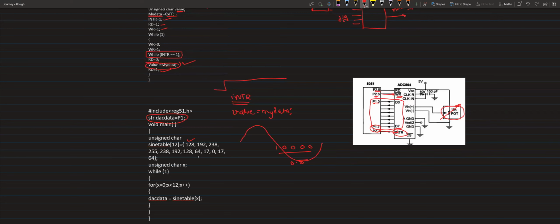If you pass these values, it is going to generate one sinusoidal cycle. So they have stored voltage samples, 12 such values. In the for loop, we will just read one value. It starts from 128 because we cannot have a negative value, right? It should start from half of the maximum value, that is 2.5 volts.